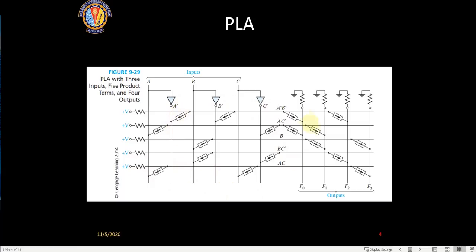Okay, so these are the programmable OR plane. The arrow which is pointing down from top to bottom here. So these set-offs. How do these become an AND plane? Initially this is a V plus, that is, the positive voltage is available on this line, right? If you give this connection out here like this, then the voltage at this line will be decided.